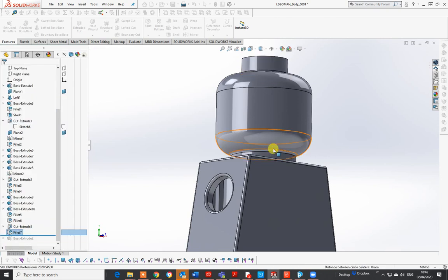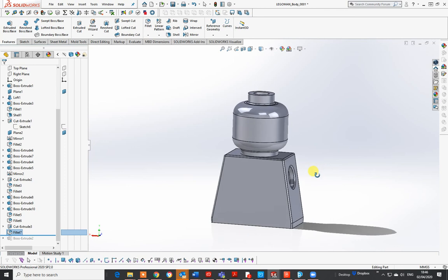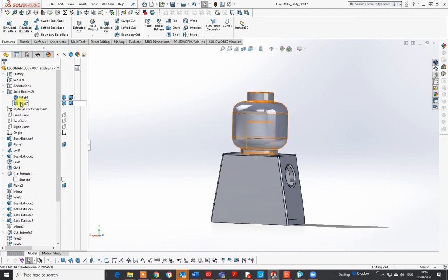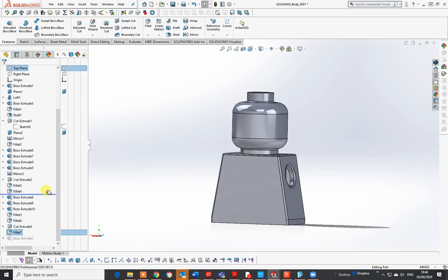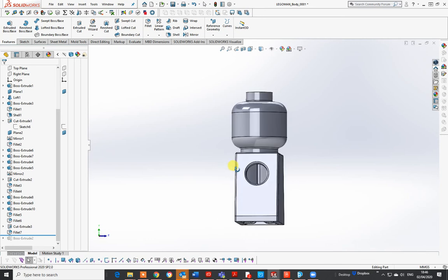Okay, that's not on your drawings, but it just tidies things up a bit. So there you go. I've now got 2 parts there. Just check the bodies folder. Okay. And I can go back in history. Just go up to there to see no head. Then I have head. There we go.